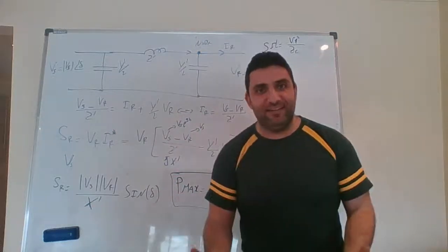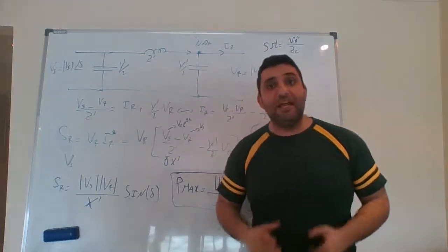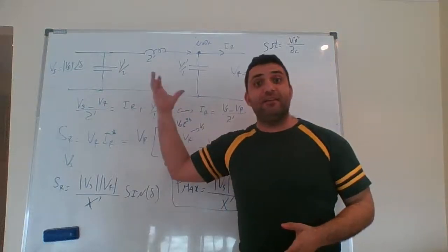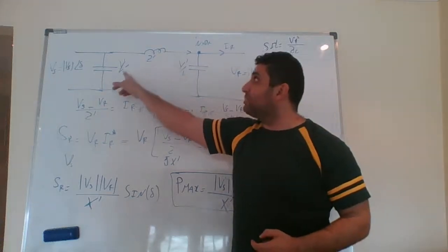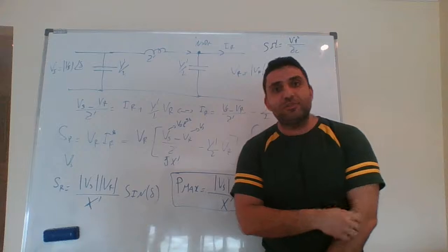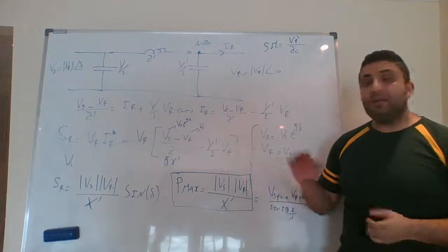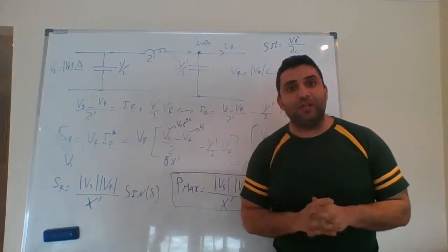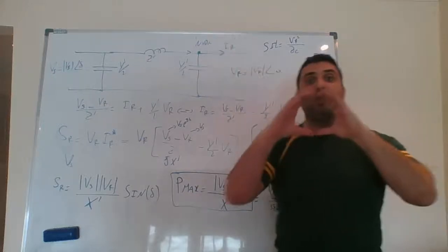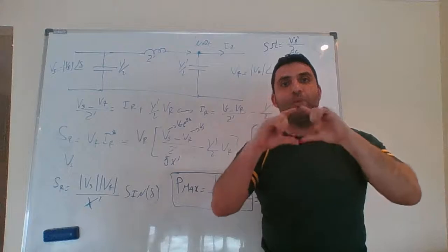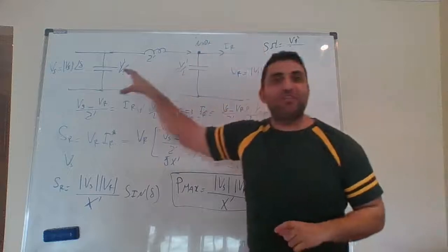Therefore, I can simplify my parameters as we saw, the A, B, C, D parameters. I can also represent using pi circuit representations by finding Z dash, Y dash over 2. Also for a lossless transmission line, all this will be in the form of cosine, sine, and tangent. And then I found the surge impedance loading. Surge impedance loading exists when I have a purely resistive load connected across the V receiving, which has the same magnitude as the surge impedance.